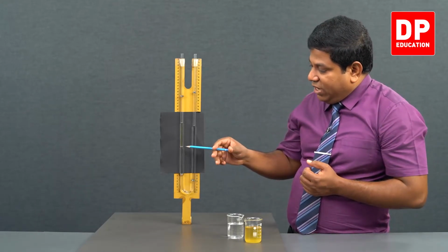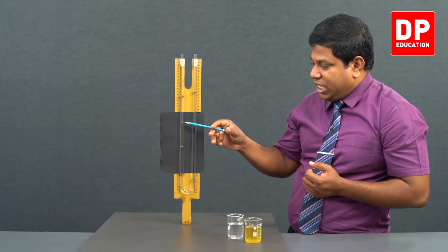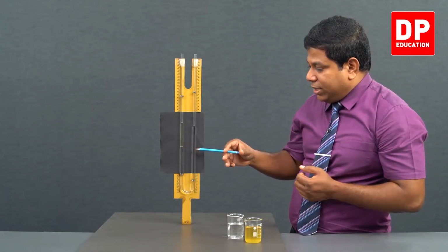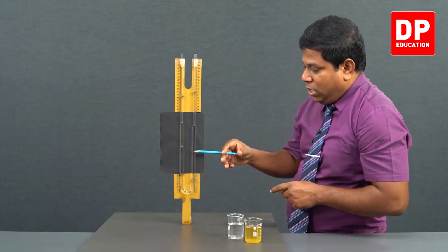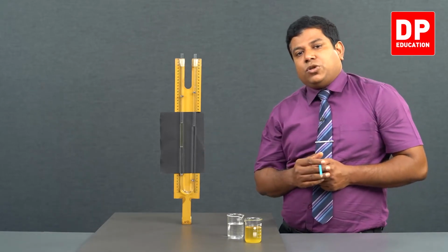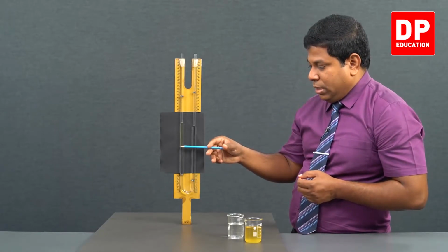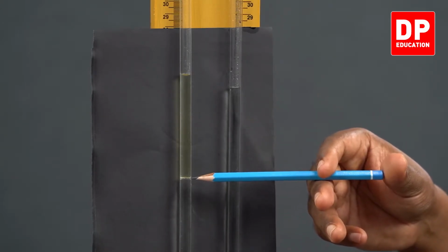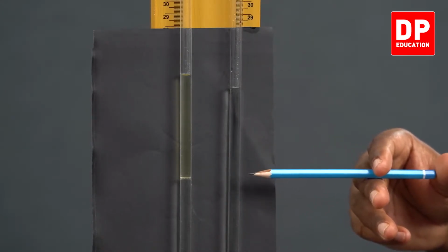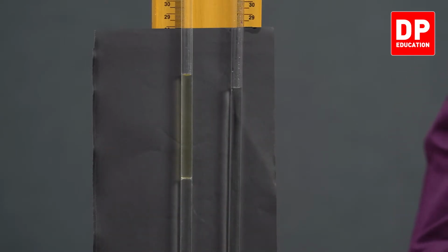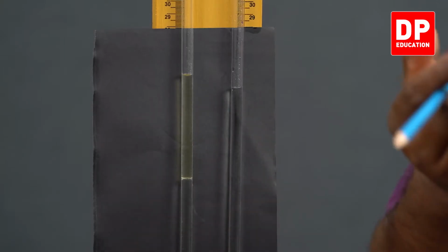So understand, at this point if I check the pressure, that pressure has to be atmospheric pressure A plus H rho g of oil. At the same height on the other side, if you check the pressure, that will be A plus H rho g of the water. Since it is connected by water, the pressure at this point and pressure at the same height on the other column should also be equal. That is what I mentioned earlier. A plus H rho g of oil, A plus H rho g of water on the other side have to be equal. From that only we got HO rho O equals HW rho W.